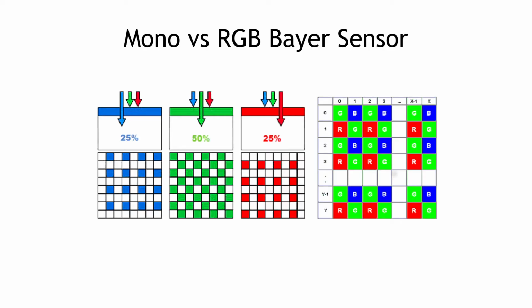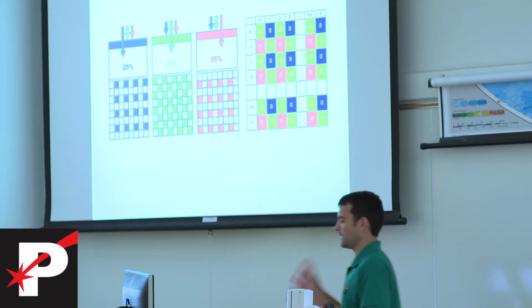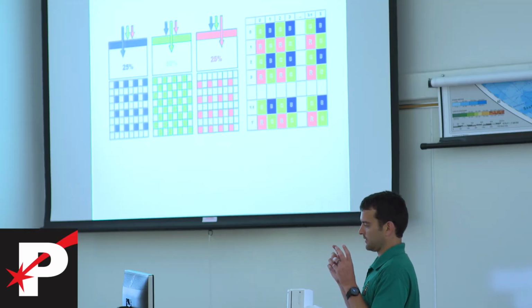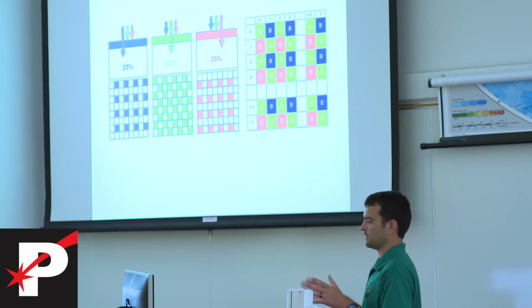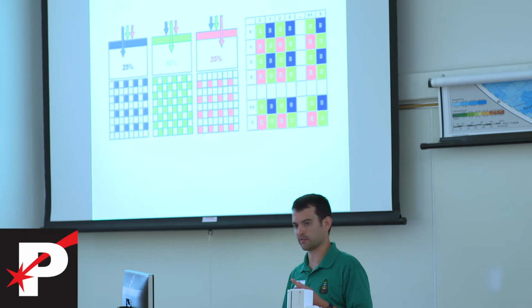If you're looking at the same exact subject, the green channel is almost always twice as intense as either the blue on its own or the red on its own. And this is why. You're essentially using a black and white sensor, and the sensor is able to separate the light with this Bayer pattern and create 3 channels from a typically 1-channel camera system.